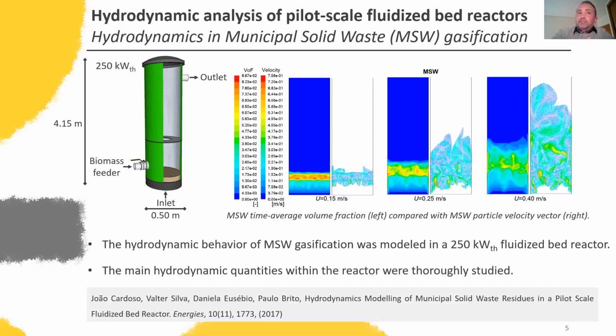In terms of efficiency, if well done, gasification could present an overall efficiency that is superior to combustion. Still, there is a lot of optimization to do to get this. In general power plants, when we have combustion, for example, coal combustion, we have an overall efficiency of around 25% more or less.